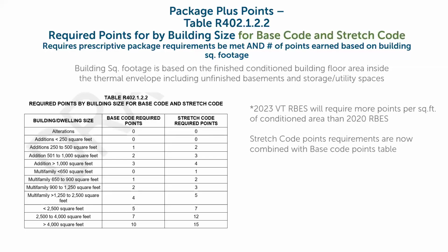Yes. Just curious, what's the state planning as far as enforcement on that U value on fenestration? Because we test for actual metric values on ACH 50s, things like that, but we're not doing some massive envelope test to see what the overall U value is on fenestration. It's kind of more just like a guideline, or they tell you what you should be doing and what you have to do, but again, no enforcement. Are there plans to actually get boots on the ground checking this thing?